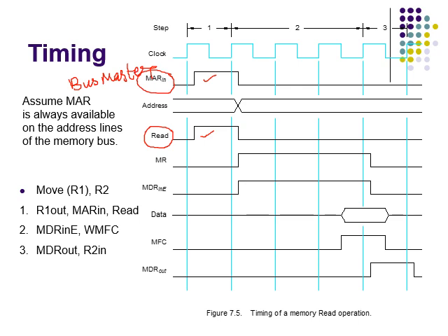When a new address is loaded into the MAR, it will appear on the memory bus at the beginning of the next clock cycle, as shown here. So it will be appearing only on the next clock cycle. A read control signal is activated at the same time when the MAR is loaded. This signal will cause the bus interface circuit to send a read command, MR, on the bus. With this arrangement, we have combined action 1 and 2 into a single control step.